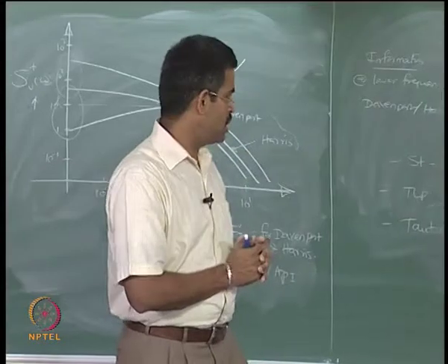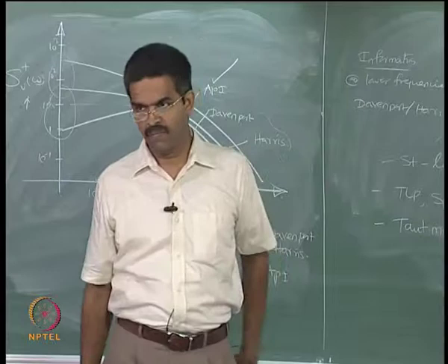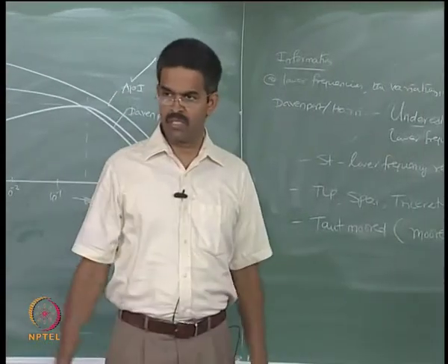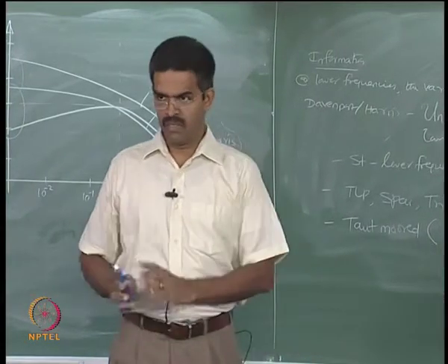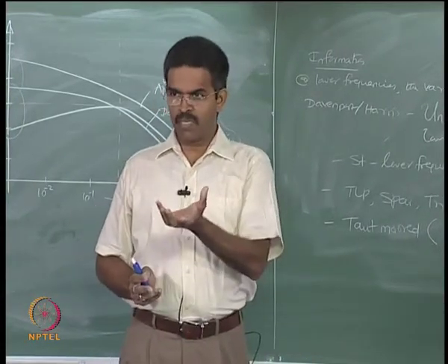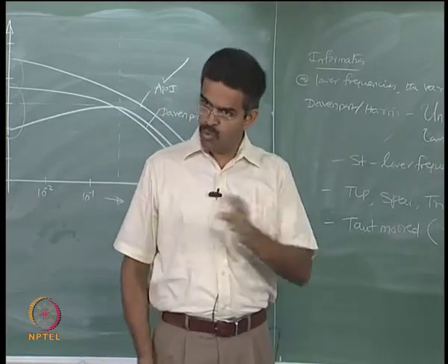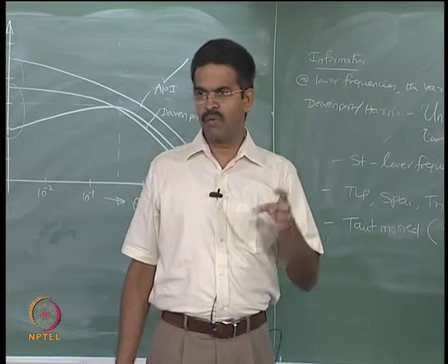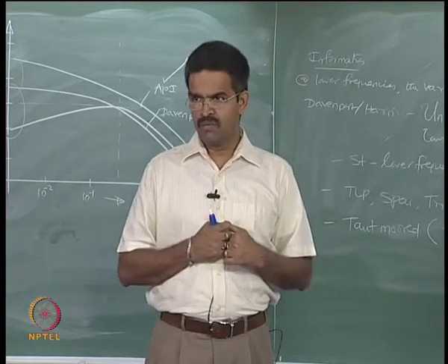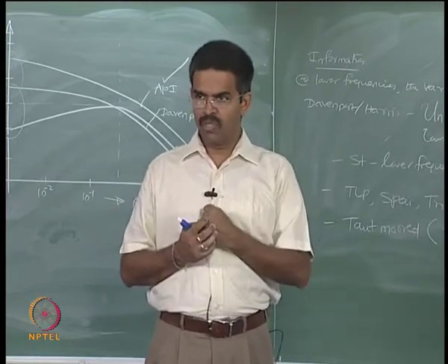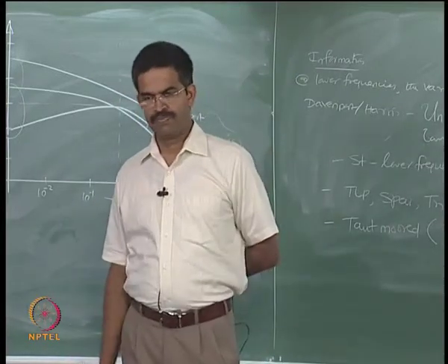Now, as far as earthquake loads are concerned, though it is a random process, we can do deterministic analysis, but as far as wind loads are concerned, people generally do probabilistic analysis. Therefore I want to convert this probabilistic analysis into a closed form in wind load computation. So I introduce what we call the aerodynamic admittance function into my calculation. With the help of that function I can compute the wind loads, which will also account for the gust factor.